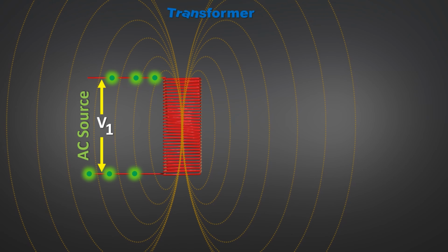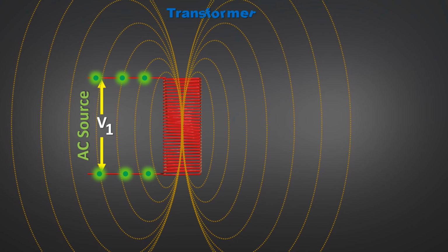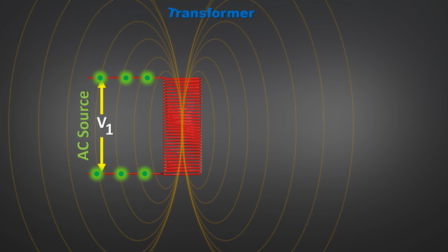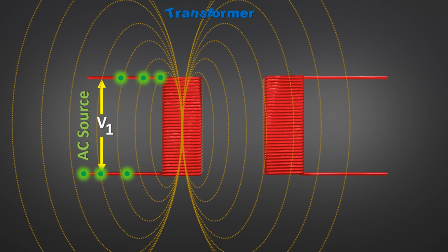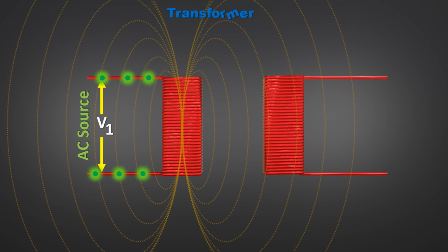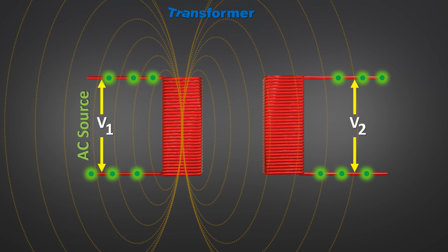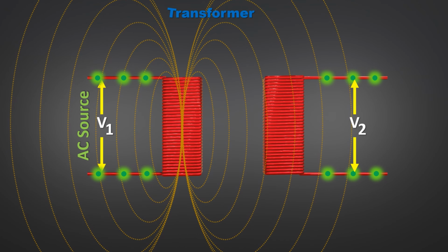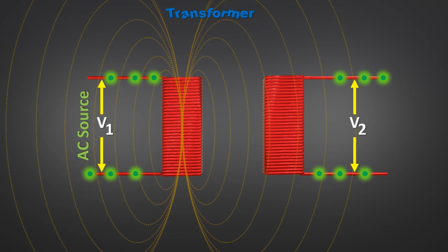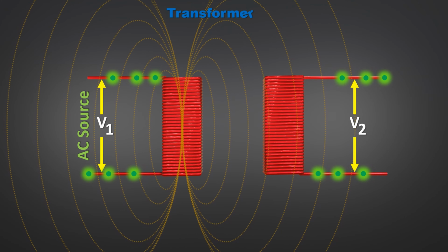We have said that there is another winding in the most basic transformer, but till now we have not discussed it. Now we are coming to the second winding in the transformer. Suppose one separate winding is brought nearer to the first winding. Then this second winding gets linked with a portion of the varying flux of the first winding. Due to this varying flux linkage, there will also be an induced EMF across it. This induced EMF would be quite small because the flux linkage is small.